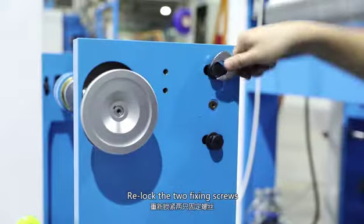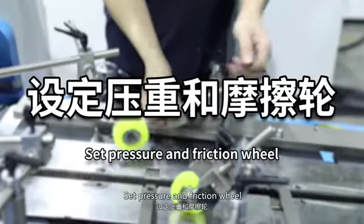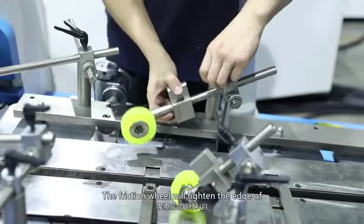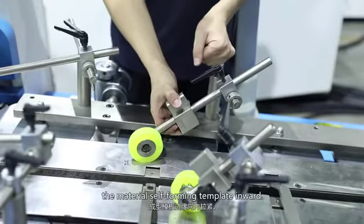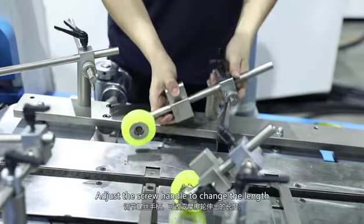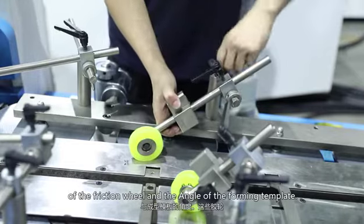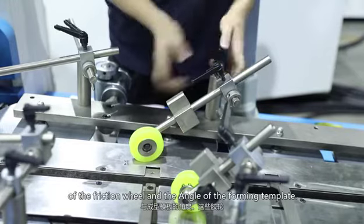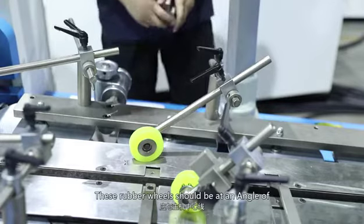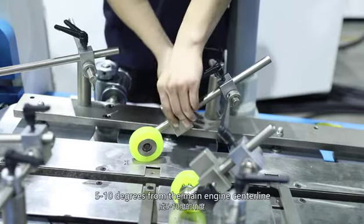Relock the two fixing screws. Set pressure and friction wheel. The friction wheel will tighten the edge of the material self-forming template inward. Adjust the screw handle to change the length of the friction wheel and the angle of the forming template. These rubber wheels should be at an angle of 5 to 10 degrees from the main engine centerline.